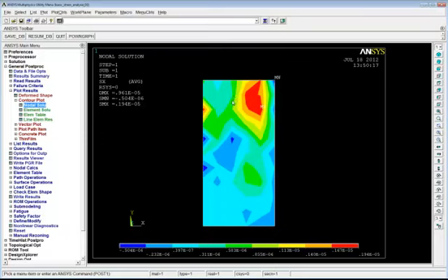It's one of the reasons why you shouldn't always trust finite element results unless you can validate them. So the only method of validation we have at the moment is the direct stress in the Y direction, and that is looking okay. Okay, so we're pretty happy here in this case that these are negligible, that we can assume there's just a constant stress in there or no stress in that direction.